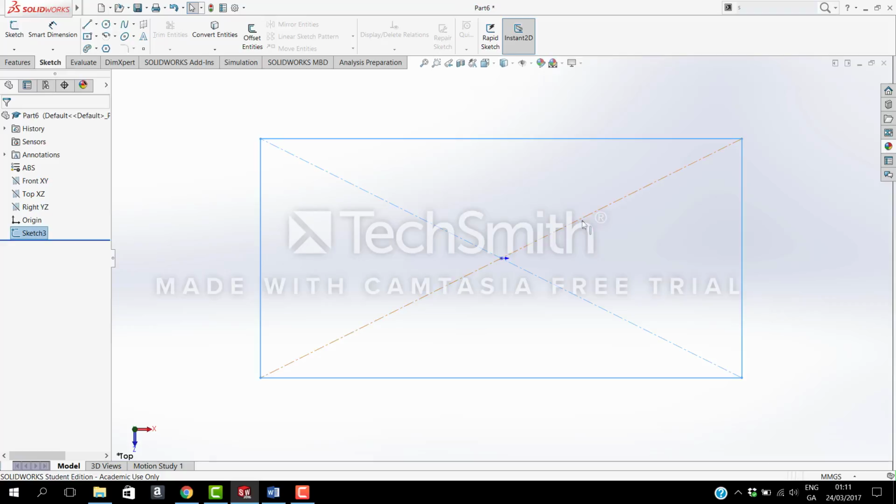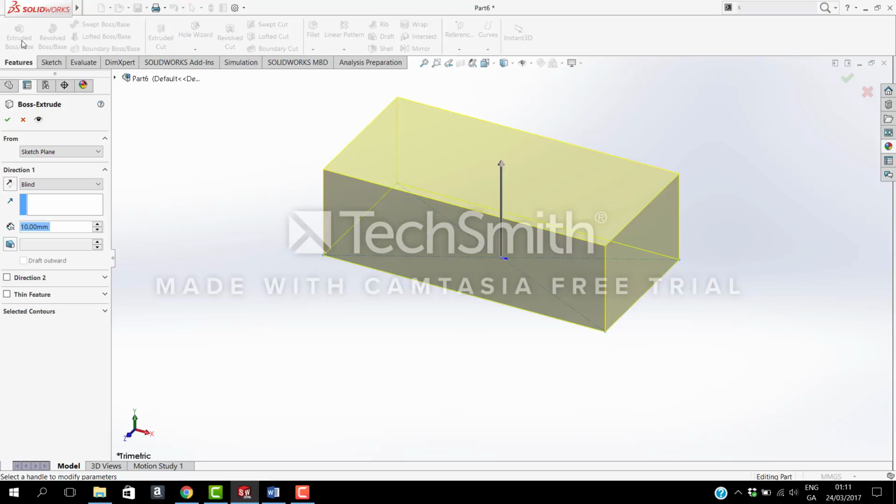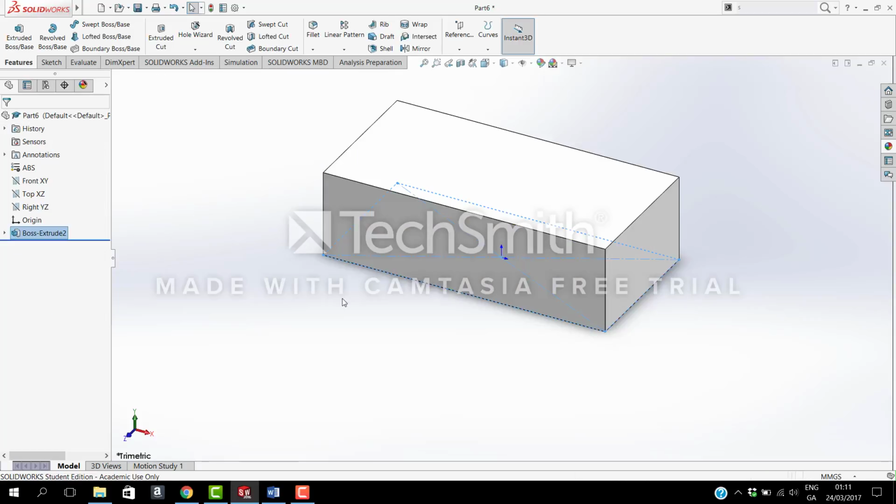Next thing I want to do is add my feature. So I click on features in the command manager and it's an extruded boss base I want. So down here in the feature manager, I can enter the depth value. In this case, it is 9.6. So I click OK. And my first feature has been created.